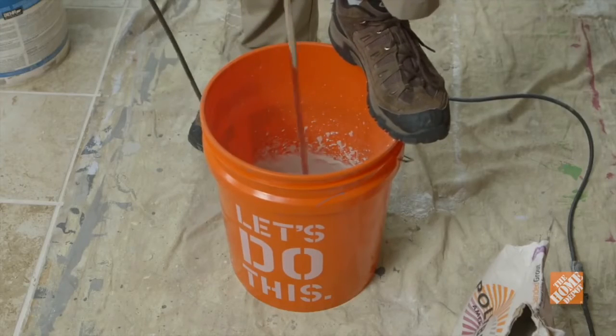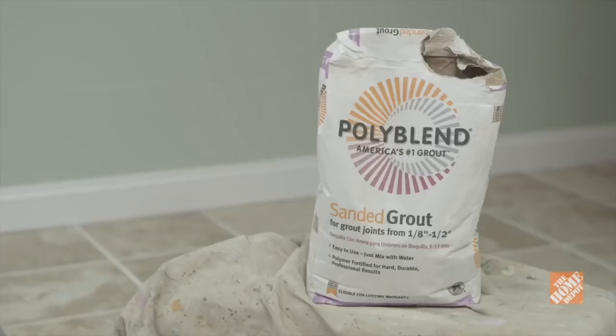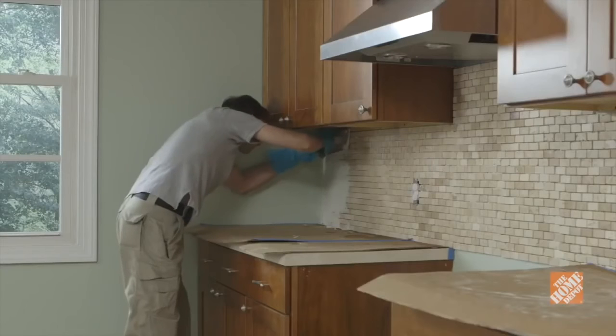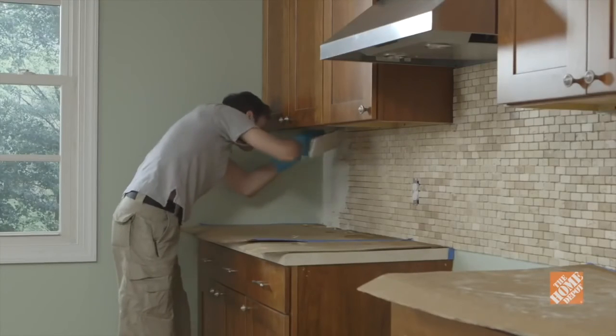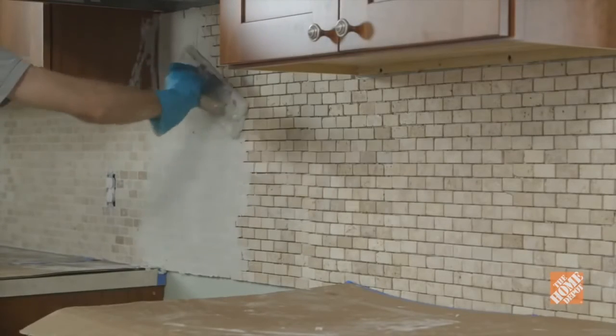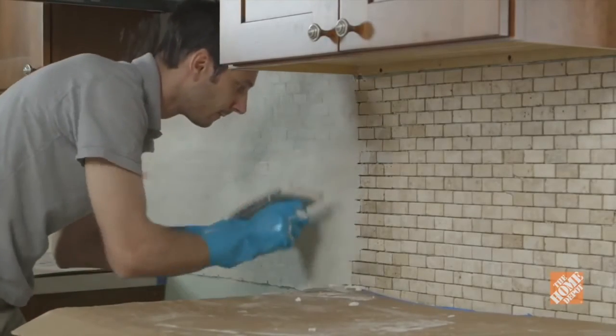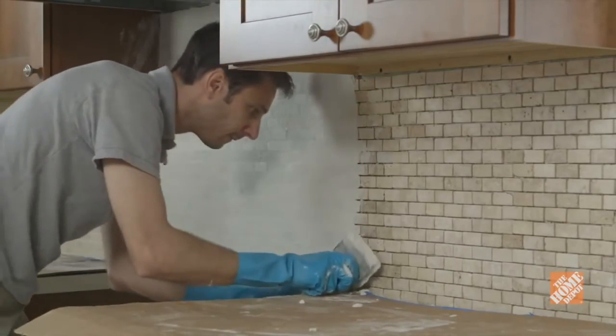Periodically remix the grout to keep its consistency. Once the grout is mixed, you'll have a limited time to use it. Generally, polyblend can be used up to 2 hours after it's mixed. Work in sections so that you can complete an area within 30 minutes. Apply the grout with the grout float at a 45-degree angle. Work diagonally. Wipe off any excess grout with the grout float held at a 90-degree angle.